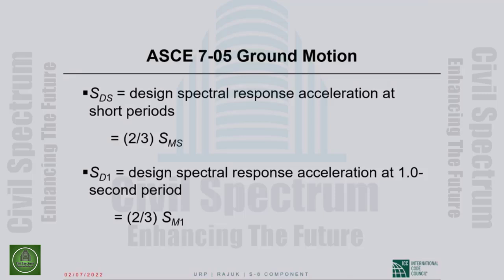The 1.5 is the margin of safety, the lower bound margin of safety that we believe is available in all structures designed by the modern seismic code, which by common acknowledgement dates back to the 1973 Uniform Building Code, the edition that followed the 1971 San Fernando earthquake.